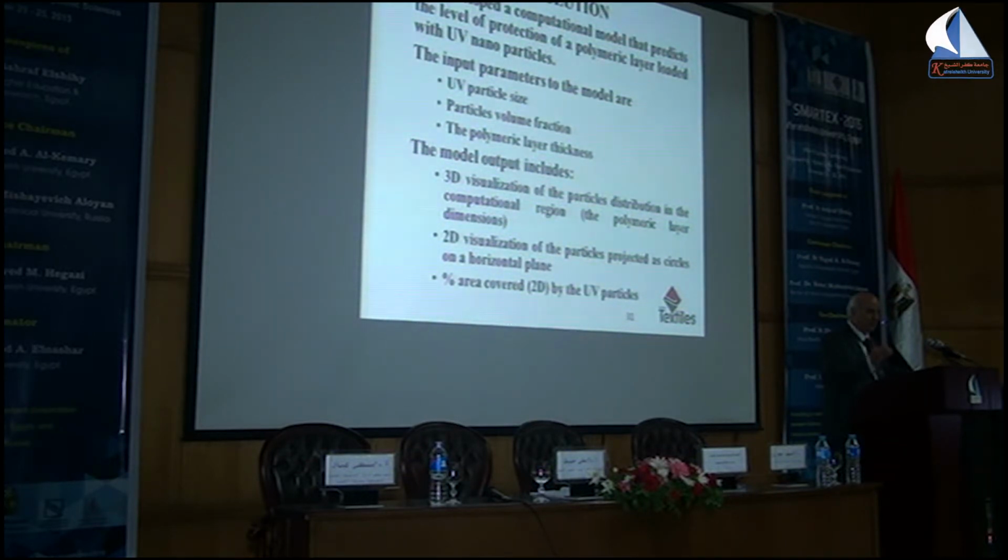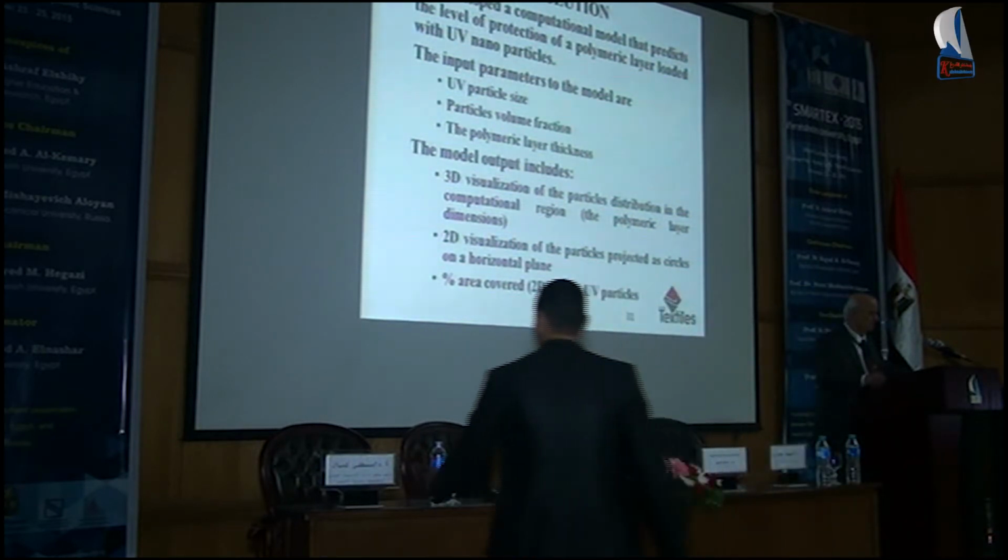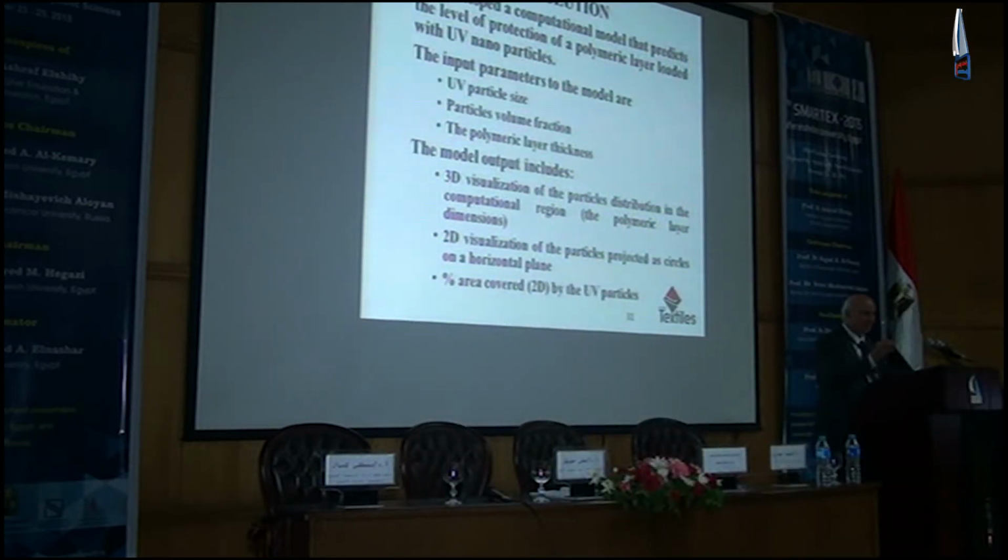When we tried to do this practically, adding these, we used several methods like twin screws while we are extruding. We extruded a film around the braid. This technology is available, and we said let's do that and see if we can really show practically that we can do that. We took SEM images of different layers, and we found out it is very difficult to separate the nanoparticles. They agglomerate, and we had to increase the thickness to achieve protection.